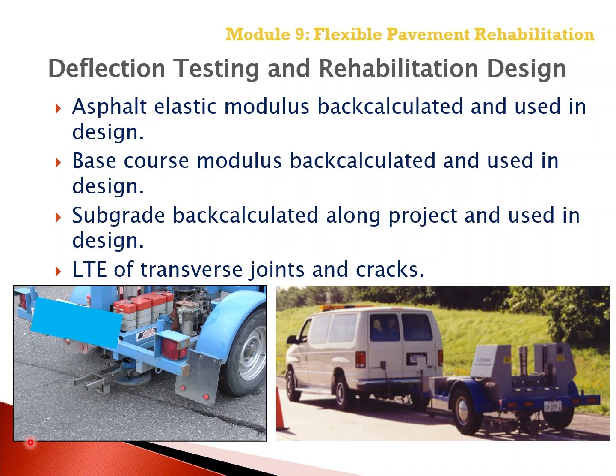The subgrade modulus, back calculated from deflection testing or deflection basins, can also be used along the project and is used in design. In fact, the back calculated layer moduli from the deflection testing can be a method to segment the project into areas that have similar back calculated layer moduli for the rehabilitation design. And again, as we mentioned earlier, the back calculated elastic layer modulus are a direct input to the Pavement ME design software.